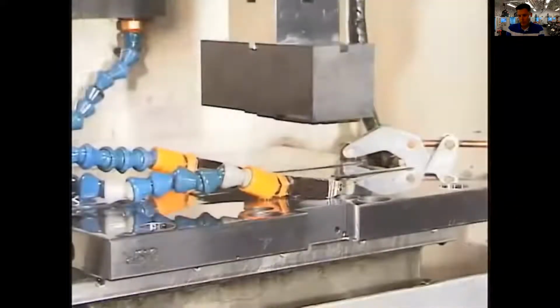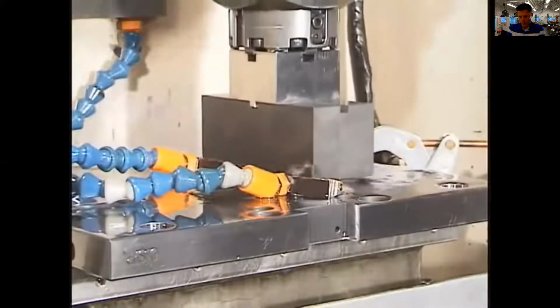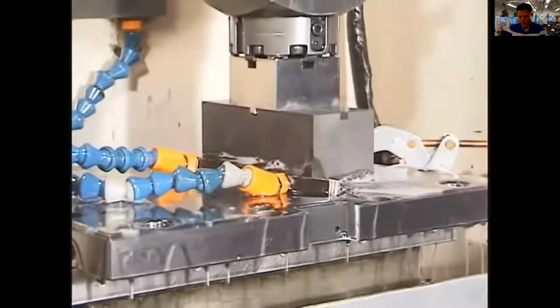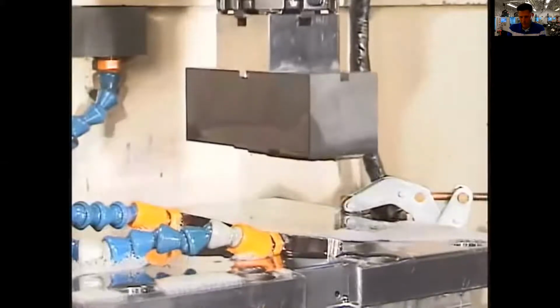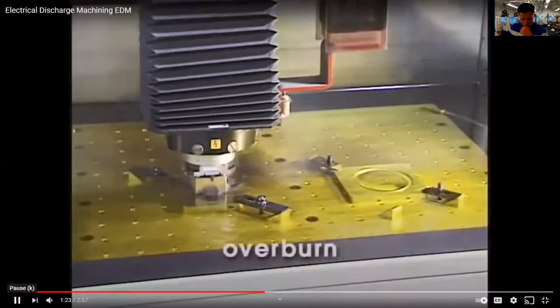One restriction of the conventional die sinker EDM machine is that the burning can only take place in the Z direction. As the electrode lowers and nears the workpiece, an electrical spark jumps from the electrode to the metal. This spark burns the metal, and dielectric fluid is used to flush out the burnt pieces, allowing the electrode to burn uninterrupted until the desired depth is reached. When the burning is complete, the result is an impression of the electrode in the metal. The distance between the electrode edge and the burnt metal is referred to as overburn or spark gap.